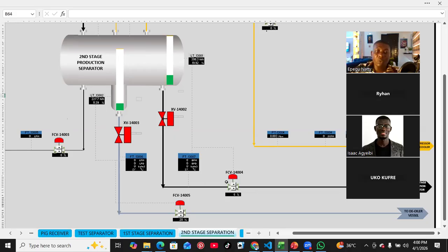But if you use this shutdown valve just for opening the line, then without the control valve, the level will just start dropping because there will be flow. We are not minding if the level of the tank goes empty or not. It is just allowing flow to pass through. So that is an open loop system. These are the various types of loops that we have.